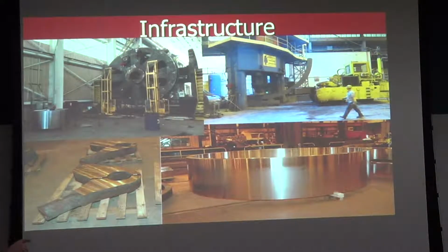That particular piece is kind of interesting because it starts off as a flat bar and then is allowed to cool, not down to room temperature, but to a point where it's not glowing anymore. And then they take that flat bar and they basically bend it by eye to get to that arc. And then they'll have a pattern that's been produced that they can check against, and they just keep working back and forth until they have the bend match the pattern that the customer asks us to work to.